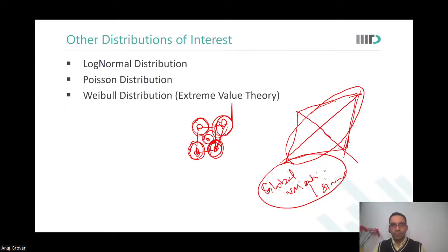Similarly, how much sigma I should qualify will change depending upon whether I choose global or the other approach. Yes, you can always modify that, but it has to come from a good understanding of probability and statistics. Don't just randomly say I will qualify only 3 sigma because I'm here. Look at how many samples we are talking about on chip, and what the marginal yield loss would be because you qualified only 3 sigma and not 6 sigma on the slow lot. But you can do that, yes, as a designer.